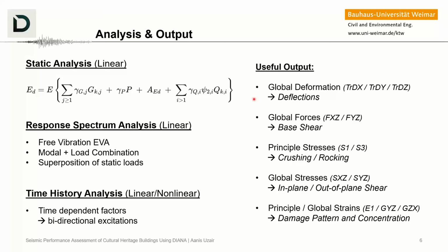We also look at global stresses because they help you understand the in-plane and the out-of-plane shear response. Although I must mention here that you cannot compare it to the shear stress limits of the material because they are shear stresses in the presence of normal stresses. So they are not principal stresses,